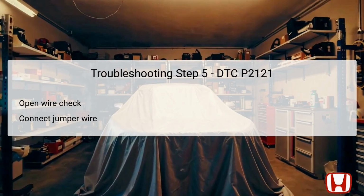Proceeding to step 5, you will want to conduct an open wire check on the APS1 line. First, connect terminals A and B with a jumper wire. Terminal A being the female terminal number 6 at the APP sensor 6P connector, and terminal B being the body ground. With the vehicle still in the off mode and disconnected connectors in place, check for continuity between the PCM connector's pin number 45 and the body ground.